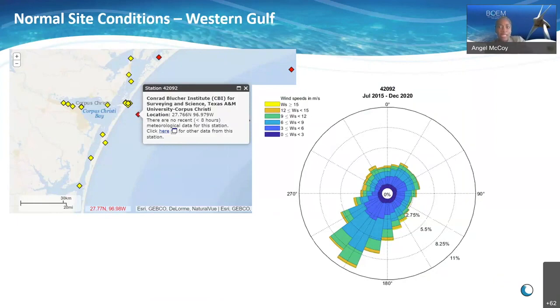So here we see that 210 degrees, or the southwest, is the dominant wind direction. And when we look at this wind rose, we can draw some conclusions about the potential shape of a wind energy area, the turbine orientation, and the potential placement of future wind facilities, whether they're upwind or downwind of an area. So keep those things in mind as we progress. Next slide, please.